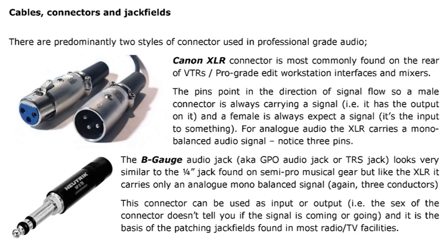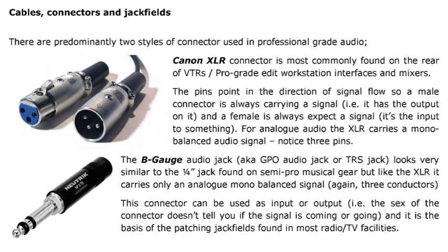The XLR is a very robust connector used for microphones. There's one there, as well as the inputs and the outputs on VCRs. And a quick thing to remember, and if this is the only takeaway you take with you, it'll be good: the pins on the XLR point in the direction of signal flow. So the connector on the right, the male XLR, is an output. You'd expect audio signals to be coming out of that connector. And the connector on the left, the female XLR, the one with the holes, would expect to receive signals.